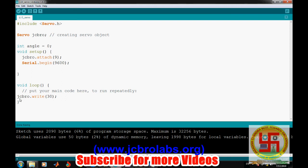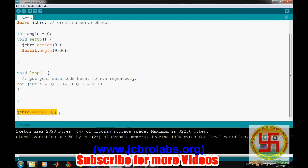Now let's create a loop here. This loop will start from 0 and keep on incrementing the angle by 10 degrees, and keep on writing the value to the servo.